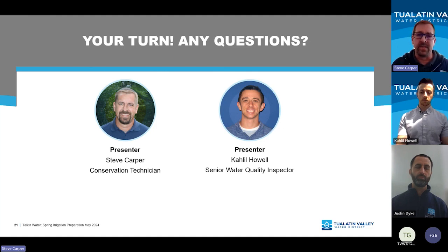There are theories that can lead to some disease, make things more conducive to that. So time of day can be a factor. But I think more likely is what we call, to get technical on you a little bit, distribution uniformity, or the overall efficiency of how the irrigation system has been designed or laid out.